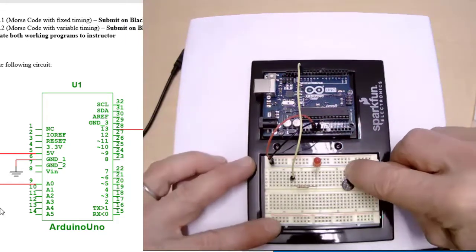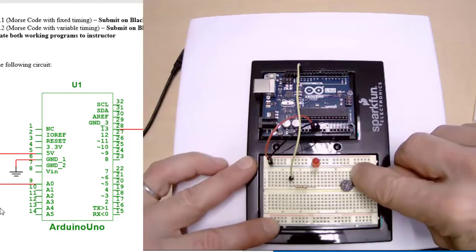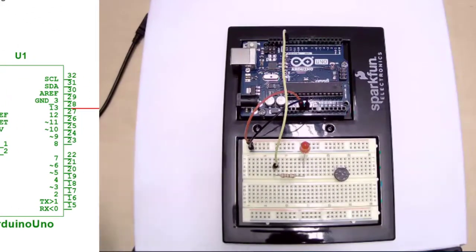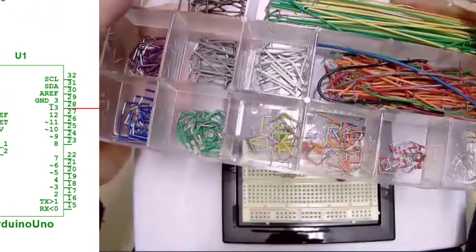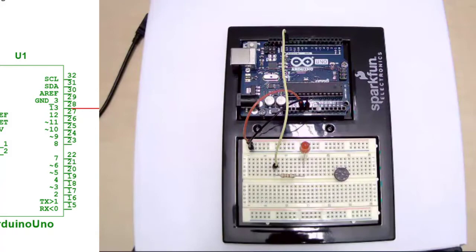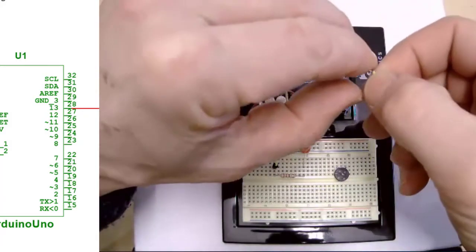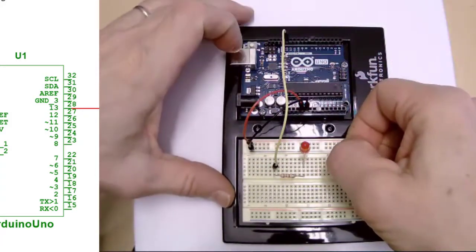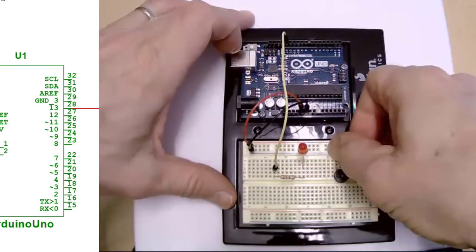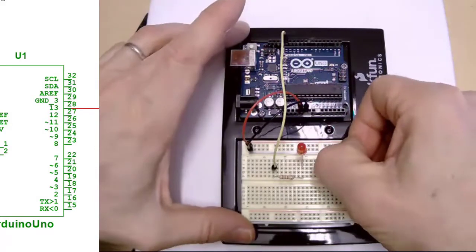So now I just have to connect the potentiometer. One of those end pins goes to 5 volts and the other one goes to ground. Now if you have a wire kit like this, or maybe a smaller version with the pre-cut wires, those are very handy because they're cut to exactly the right length. If not, you can certainly use some of the jumpers that you've got, but I like these because they make very short direct connections. So I'm going to connect one of these to 5 volts and the other one to ground.